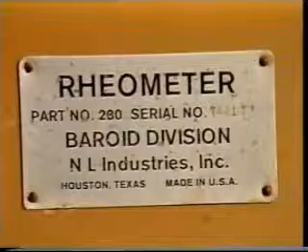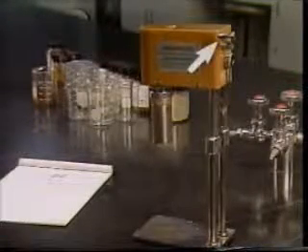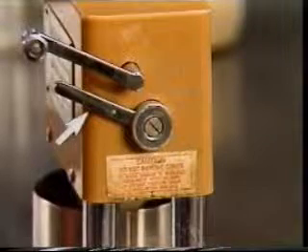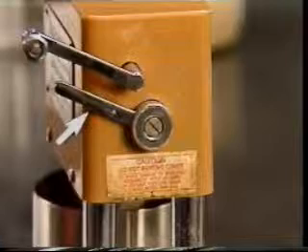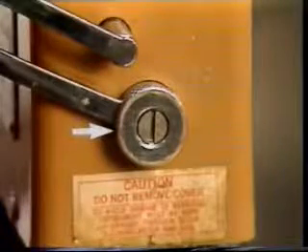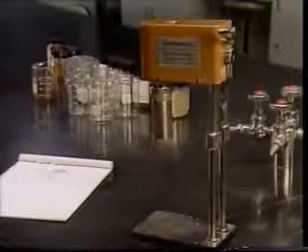The rheometer is a portable rotational viscometer, powered by the operator turning a crank which drives a spindle through a precision gear train. Speeds of 300 and 600 RPM are selected by a shift lever. Rotation for gel strength measurement is accomplished by a knurled knob. The test procedure is as follows.